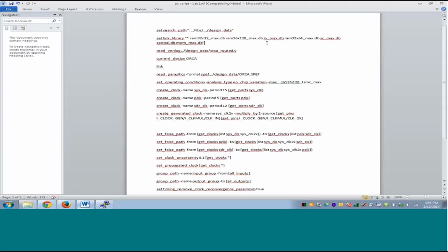It is a very common phenomenon because for each of these the vendors might be separate. The standard cell vendor is usually separate from the memory cell vendor. Even if the same vendor is providing the library, they will prefer to separate these out. They will give standard cell as one deliverable, memory as another, IO as another, PLLs as another. So your full chip STA link library list will be pretty long. So we will set this.